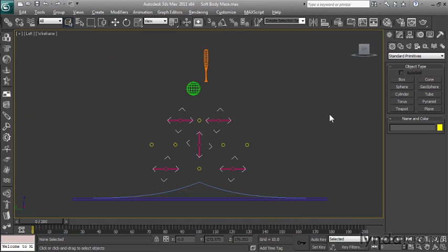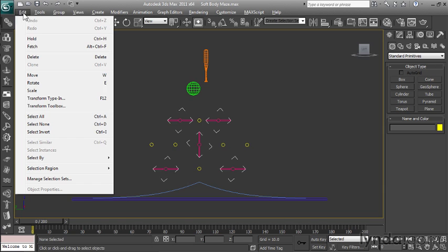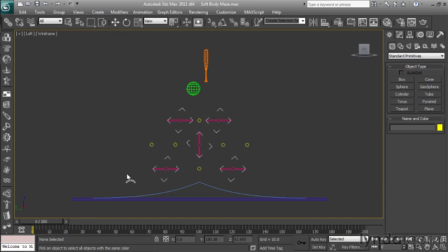Okay, the yellow wireframe objects are our scene's stationary pegs. Each will look and act the same during the simulation. Because of that, we can set the properties up for each all at the same time. To select them, let's use a handy selection tool in Max that lets you select things by their wireframe color. You'll find the command in the Edit pull-down menu in the upper left-hand corner. You'll choose Edit, Select By, then Color. We can now position the mouse on top of any yellow object and click.